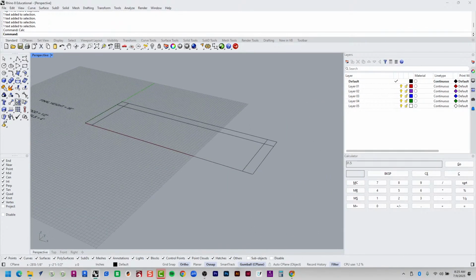And what I'm going to do is I'm going to start off by creating some 3D boxes. When I do my boxes, I like to use box 3 points height. So I'm going to click on this one. Oops. And I'm going to start of edge will be here. Okay. End of edge will be here. Width will be here. And then the height is 31.5.